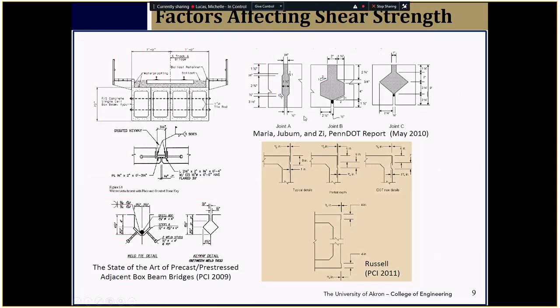Another thing that's interesting is quite early on, more than 10, 15 years back, it has been recognized that the joint is a real problem, and many researchers studied the joint performance, to the extent that for railroad bridges, they use two post-tension strands to tie together the boxes. And then there are many other mechanical attachments.